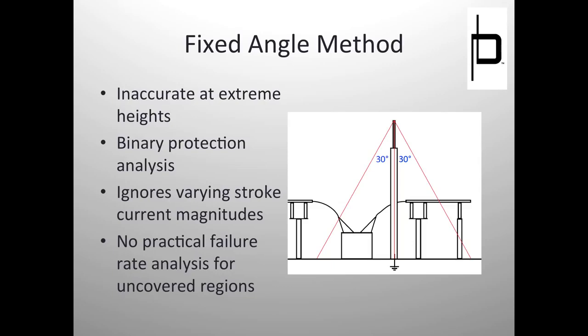I'll give you an example. The best example is something like the Empire State Building. If you imagine it's a grounded structure, it itself is a lightning mast, and it would provide this gigantic 30-degree cone of protection around New York. I know you used to live in New York. I don't know if you lived inside the 30-degree cone of protection of the Empire State Building, but we find that a lot of buildings inside its 30-degree cone of protection actually do get struck.